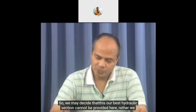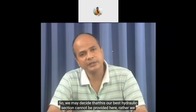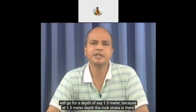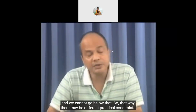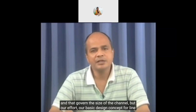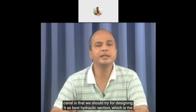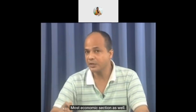So we may decide that, okay, our best hydraulic section cannot be provided here. Rather, we will go for a depth of say 1.5 meter, because at 1.5 meter depth the rock strata is there and we cannot go below that. So that way there may be different practical constraints, and that govern the size of the channel. But our basic design concept for lined canal is that we should try for designing it as the best hydraulic section, which is the most economic section as well.